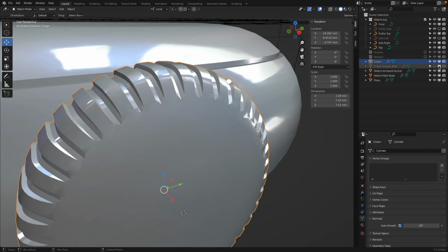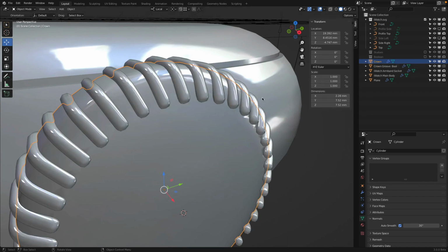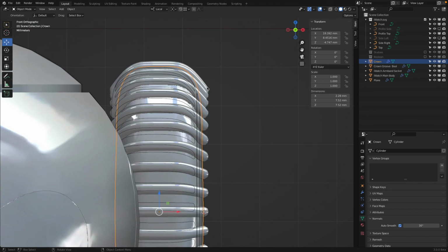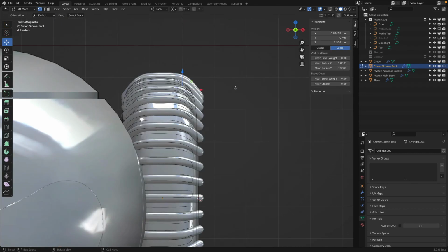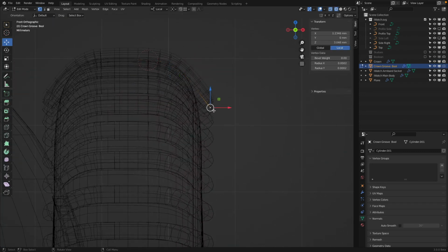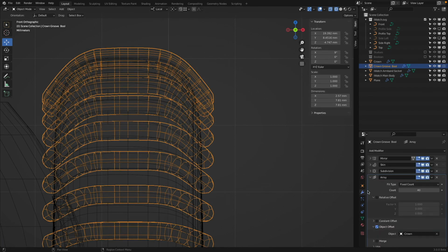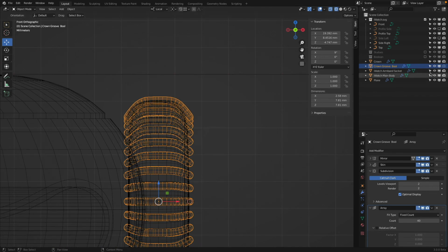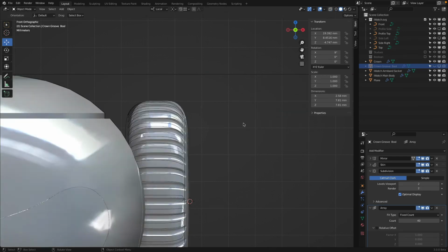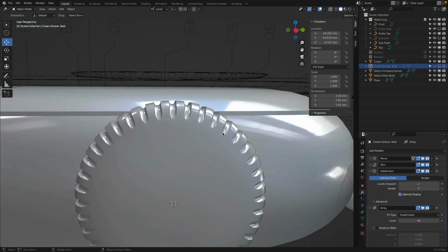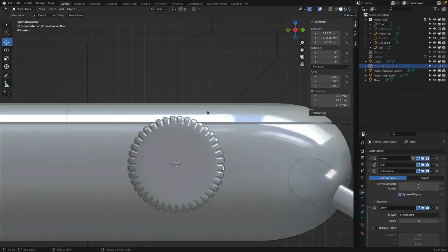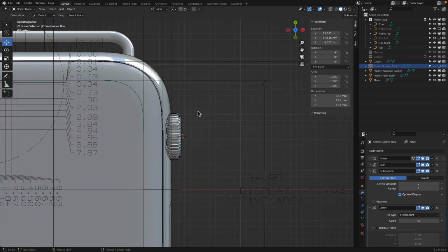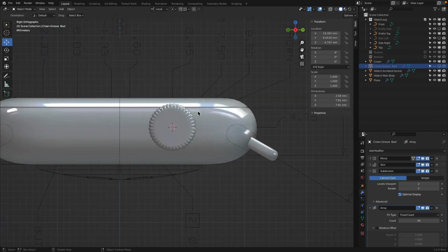Now crown groove needs to have maybe a little bit more of detail. So these endpoints, and actually this endpoint is good, but what needs to change is the subdivision goes one up. So it's not so sloppy. Yeah, better. There. That's how you make the groove.